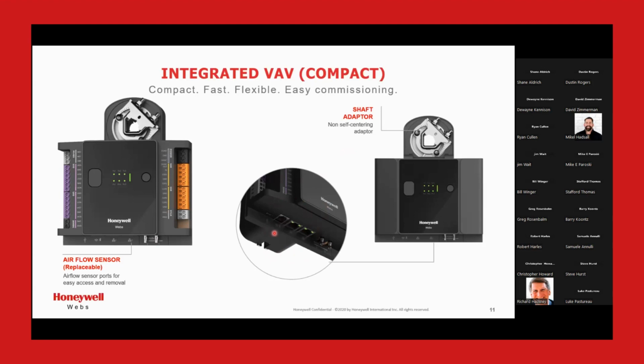There are 2 other differences that set it apart from some of our earlier VAV products. Not shown on the graphic, the actuator has position feedback. That is a big, big, big deal. This is Honeywell's first VAV controller where the damper position is measured directly off the actuator, which means technically you don't need to do a float out sync anymore. I know where that damper is at all times because I can read that value directly off the actuator. So this can eliminate the need to do a float out sync.